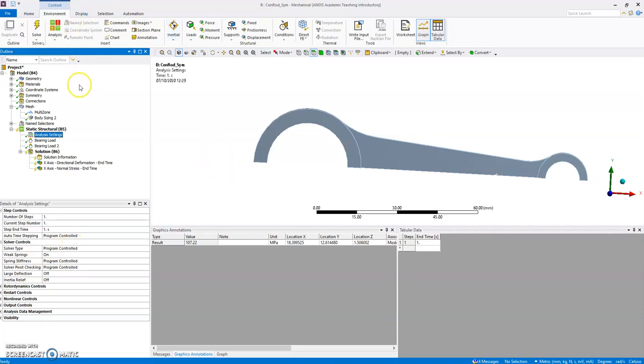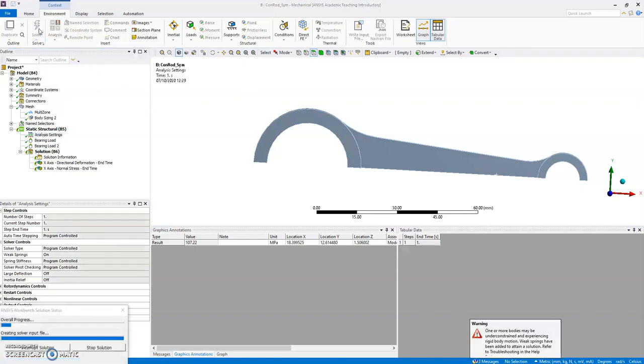Okay, so that's done. Let's do it. Which I had done before. I forgot to turn it on, but by default it's off. What they do basically is apply some very small spring at each node to essentially drown out numerical errors due to slight imbalances in the mesh. It's a nice way to get rid of very small numerical errors, but it basically makes the part drift, and that would not be good.